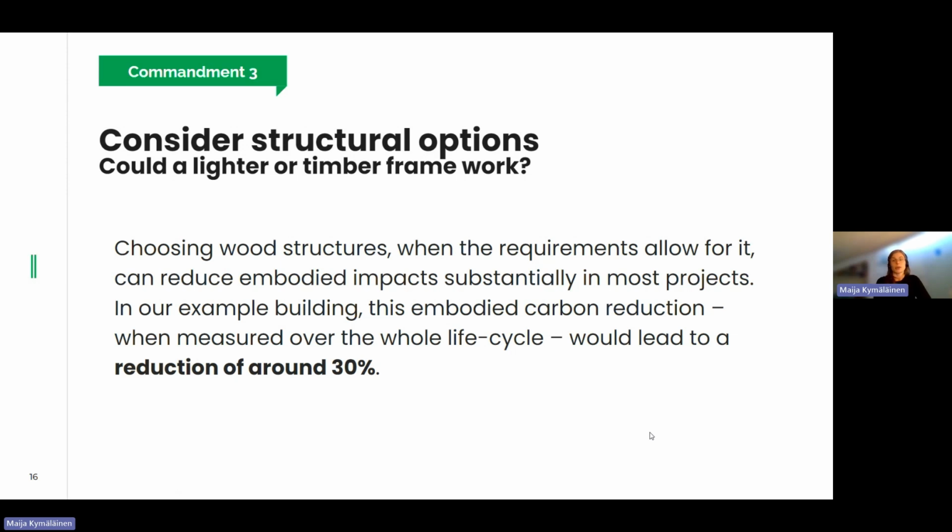Wood materials require quite little energy to produce. For example, for concrete, you would need the excavation of minerals, the transport of heavy materials, the crushing, thermal processing, and the emissions due to calcination and so on. And for wood, you basically need energy only to harvest and transport. And sawmills usually require very little external energy, because you can use the residues such as bark or sawdust to create the heat for drying and other processing. So the emissions there are quite small.